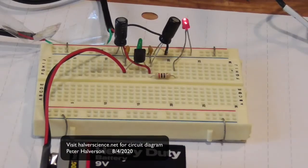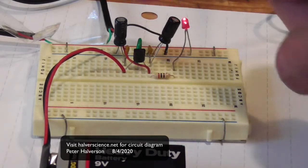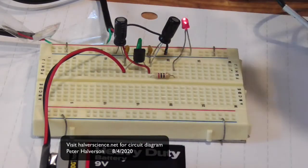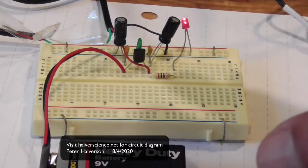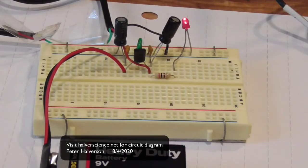Some cautions. When you make this sort of power supply, you've got to be careful. Make sure before you hook things up that you really are sending 5 volts this way. If you send 9 volts to the FPGA board, you'll break it. Similarly, make sure that you're not sending power back to the computer. That'll break your computer. So just be really careful before you commit.